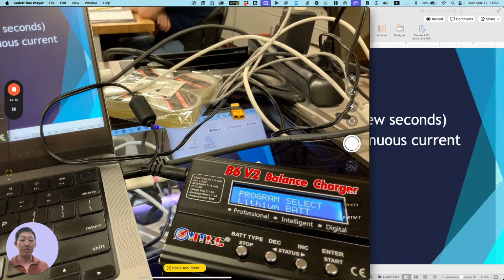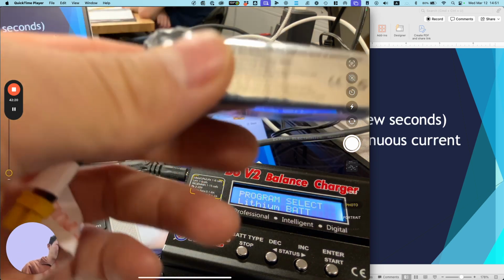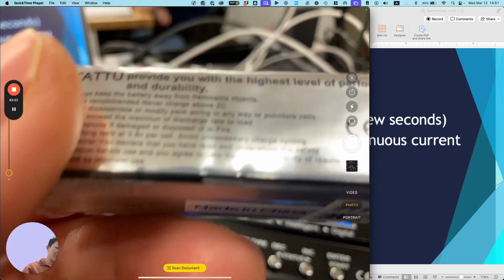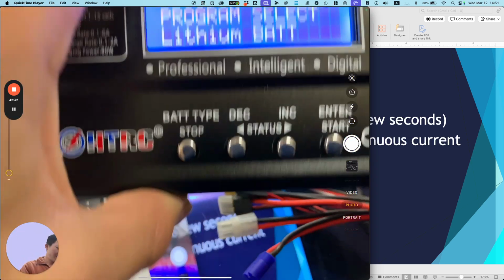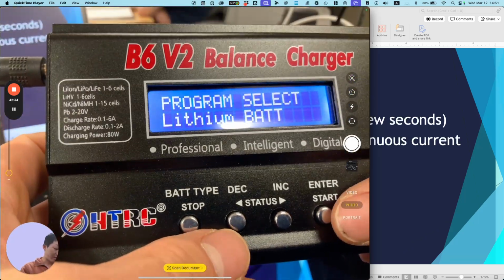Okay, you don't need a charge cycle for this. If you're familiar with older batteries, they have a memory effect, and you're told to discharge and charge them up. But you don't have to do that with lithium-ion batteries. Just make sure that they're happy in terms of the voltage, so don't drop it too low, and also the temperature. Don't leave it in the cold or in the heat. Okay, let's look at an example charger here.